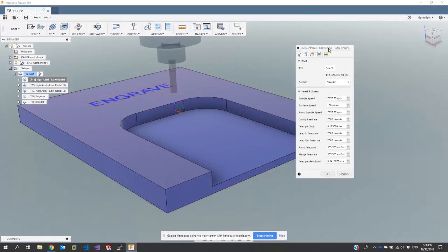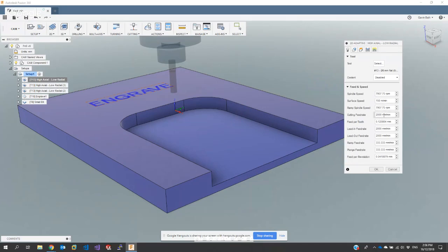Stop you there for a second, Gavin? Sure. Just so everyone knows, the minimum speed on the Makita is about 8,000 RPM, and then it goes up to about 32,000 RPM. And obviously with most air-cooled tools, not only the Makita, but spindles, the slower you go, the hotter the spindle is going to get. So if you can run higher RPMs, the spindle's just going to last longer, and you're going to be able to operate the machine for longer as well. Oh, that's good to know. I didn't realize it couldn't go slower than that. I need to put a tacho on mine at some point and find out what speeds I'm actually doing.